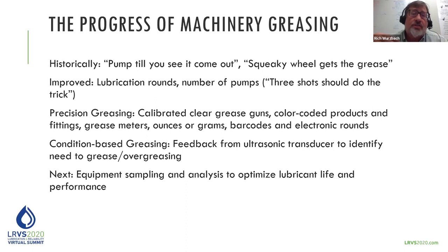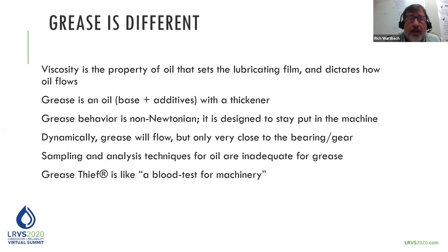It allows us to go from pump until the grease comes out somewhere to now having some kind of feedback mechanism. And I'm going to say that the next step along the way would be to incorporate equipment sampling and analysis to optimize that lubricant life and its performance over that life.